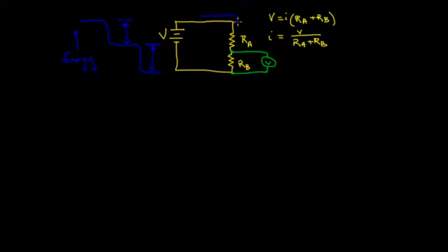That's analogous to the current in our circuit. Energy, or voltage, is spent in driving current through each resistor. The energy dropped going through the first resistor is the current times the resistance, or I times RA. At this point, there's still voltage to be dropped across the resistor RB. Again, that energy can be calculated from the current times the resistance, or I times RB.